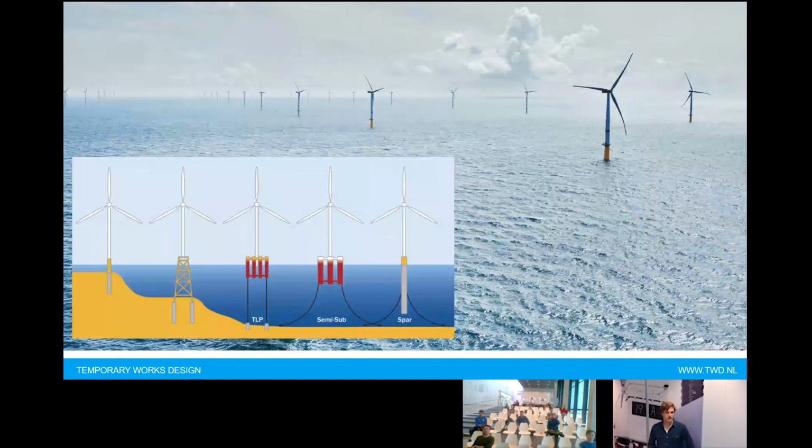Also, a nice side note here is that most of the windmills currently are placed in shallow water, like the North Sea. I don't know if you know a bit more about it, but the North Sea is about 40 meters deep, so it allows for easy installation, let's say, of those windmills on a single basis with one monopile. But if we go deeper and deeper, there will be different methods required in order to place those windmills safely.